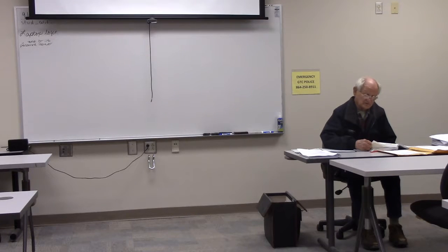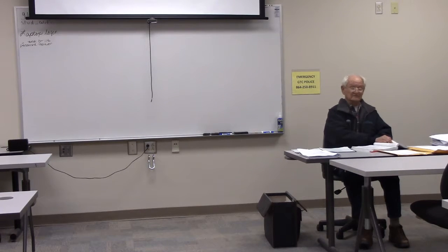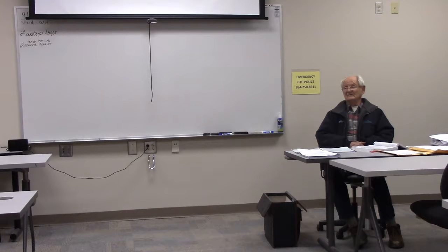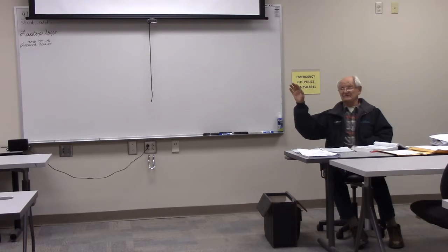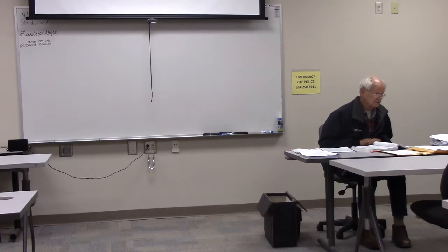All right, so therefore a cable containing two wires that passes in and out of an outlet box without a splice or tap is counted as two conductors. However, a wire that enters a box and is either spliced or connected to a terminal and then exits again is counted as two conductors. So if you've got a wire coming in and a wire going out, it's the same wire, but you're making a splice in that box, that wire will be two. If you don't have a splice in the wire, if it just pulls straight through, it's one conductor in that box. If it splices or terminates, it counts as two.